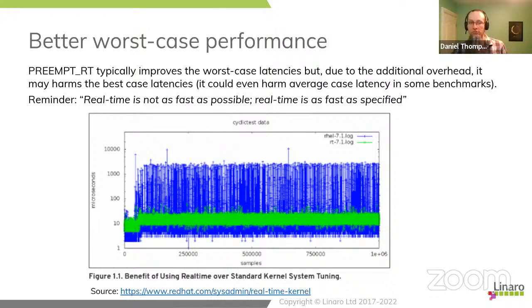It's quite possible, if you've got systems where you can engineer in buffering to mitigate latency, to measure the typical performance and then set the buffers to a higher level than that. And then you don't need to go through the complexity of debugging preempt RT and things like that, or pay the performance costs. So it's not always the case that you dive straight into preempt RT.